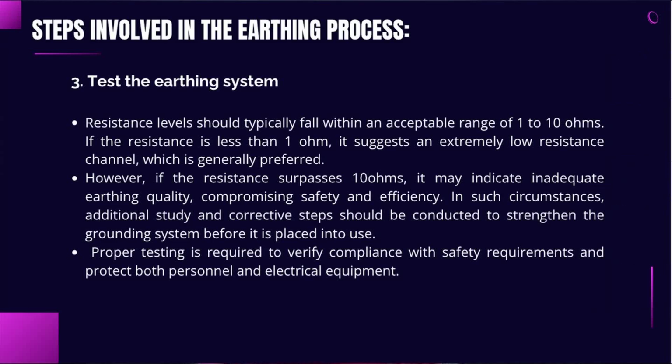Resistance level should typically fall within an acceptable range of 1 to 10 ohms. If the resistance is less than 1 ohm, it suggests an extremely low resistance channel, which is generally preferred. However, if the resistance surpasses 10 ohms, it may indicate inadequate earthing quality.